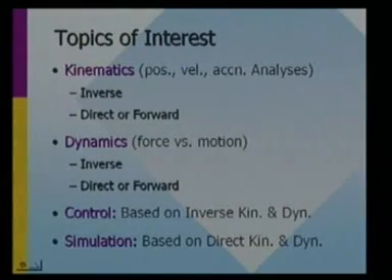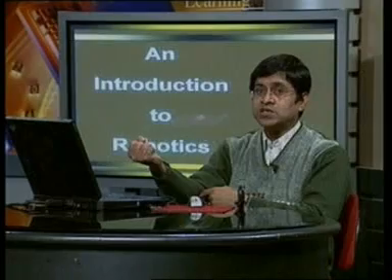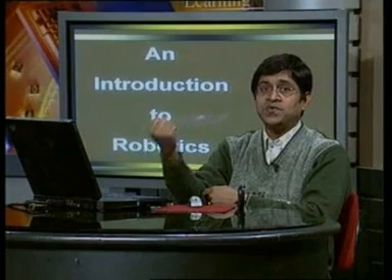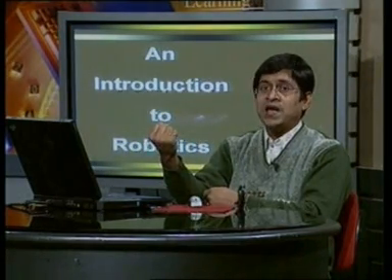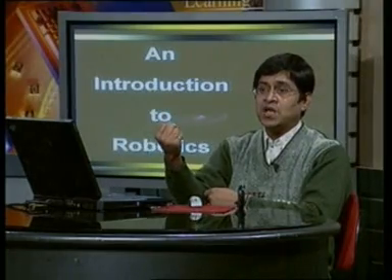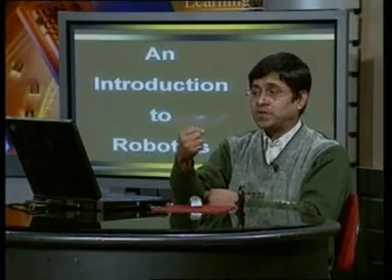In dynamics, we do the force studies, right. So, again in the inverse, what we do, if you give me this motions, then how much force I will be requiring, that I calculate, that is called inverse dynamics. In direct dynamics, if you give me this force, I want to find out how the motion will be happening.